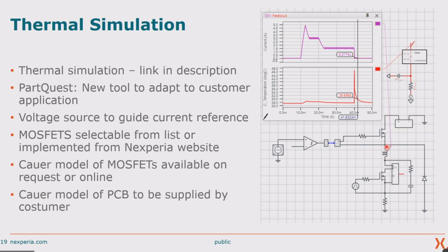So once the MOSFET blocks the current, the inductor will develop a voltage that is in reverse. So it will go to the negative, and the diode will start conducting, and due to that, that voltage across the inductor itself will be transferred to the MOSFET and take the MOSFET into avalanche.